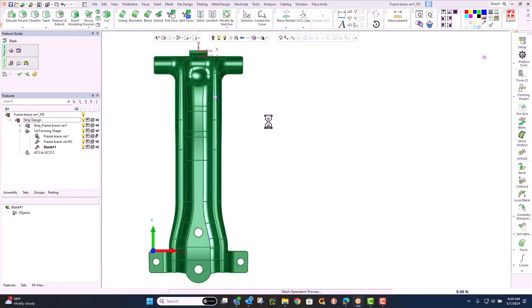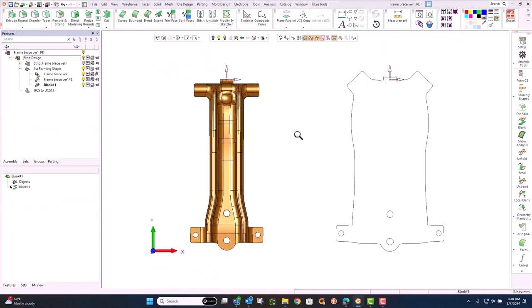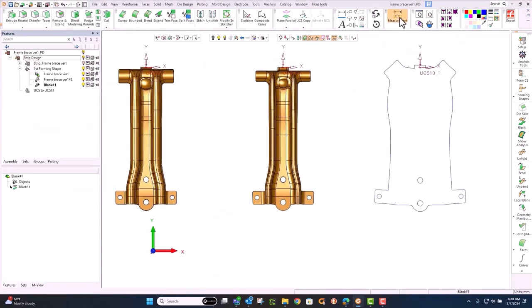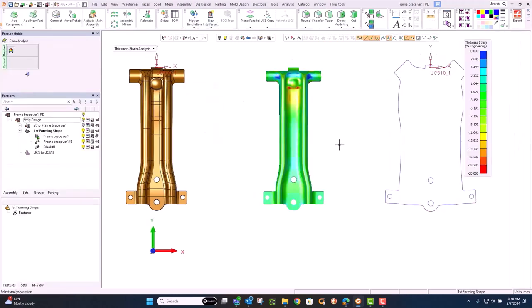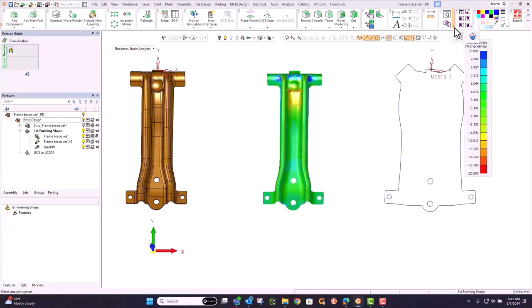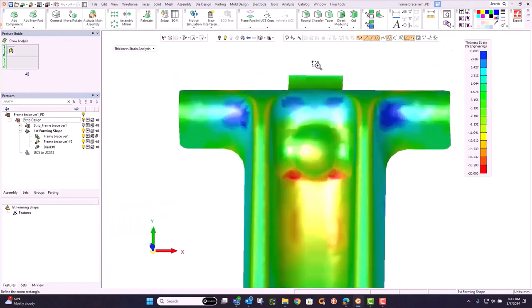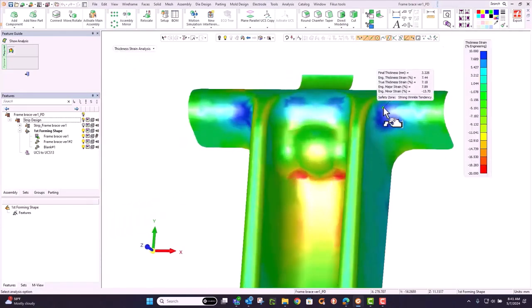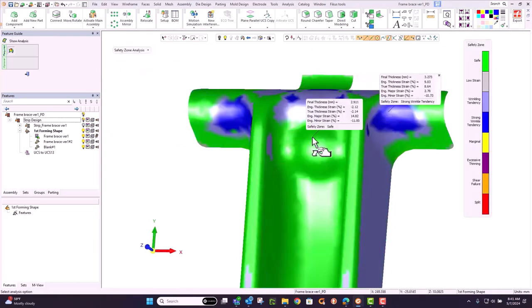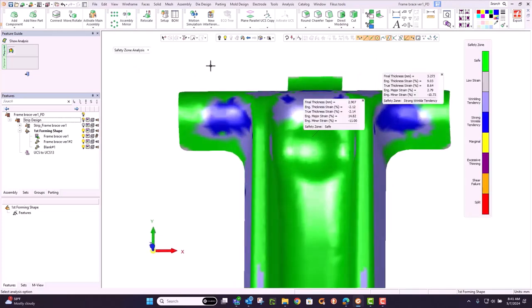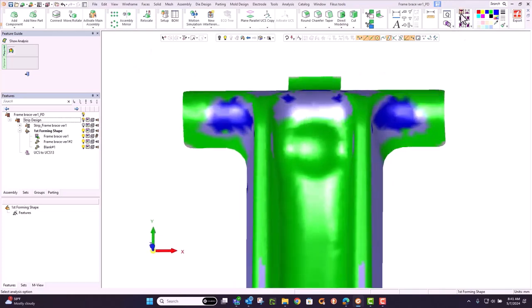What are we dealing with when it comes to looking at formability? This allows us to do an FEA analysis where we can check on what areas might wrinkle. Here we're doing a quick check to see on the overall perimeter of the part. Zooming in here, you can see that the blue area is showing where material is gathering, whereas the red shows the potential of how it could be thinning. Here we're identifying wrinkle zones. All right, so we know that there's the tendency to gather material in those corners. All in all, it quickly helps us to see what's involved in forming this part.